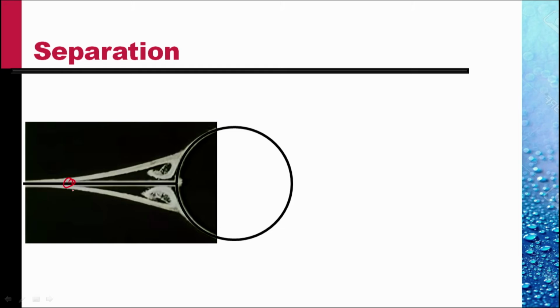And we have vortices formed here in which the fluid is recirculating on top. This did not happen when there was no plate, because though the pressure was increasing, there was no wall on which a boundary layer was developing.